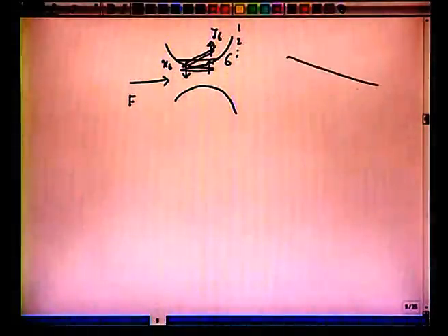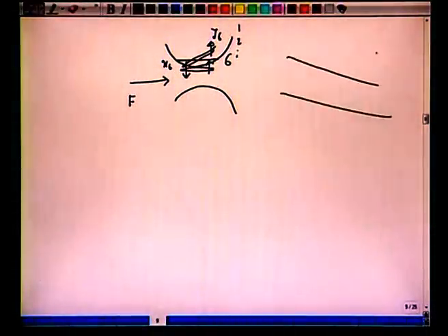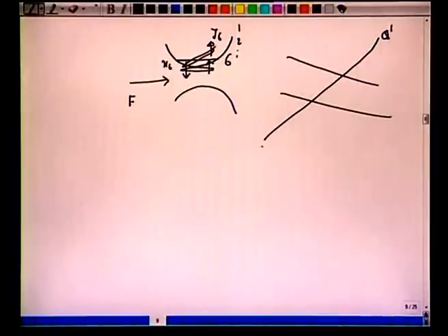On this graph, with the previous graph, this was your line which was meeting Q dash and Q double dash with F here, zF or xF, the feed points. You should be able to obtain 6 complete stages. In the 7th stage, you will see that the tie line crosses the big line. Now we are here. That means now we have completed your rectifying sections, and now we have to work on this W, del W, instead of del D here.